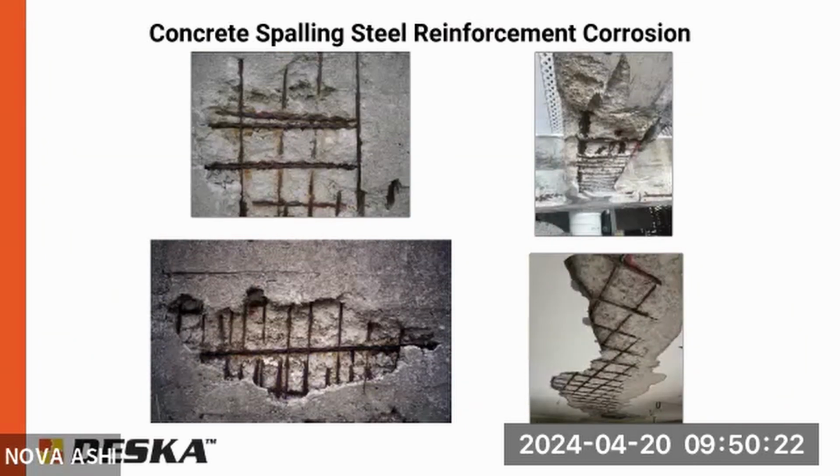We have this. It doesn't occur too often in residential construction, but it depends. If you have spalling of concrete slabs or spalling of concrete walls, concrete beams, balconies. Essentially, when water gets into that concrete and it touches the steel, it corrodes the steel. Just like the lintels, the steel begins to expand. Typically, they say it can expand up to about 10 times its original size. So most lintels are 1/4 inch thick. That lintel could be over an inch thick, depending on how long you let it go for.